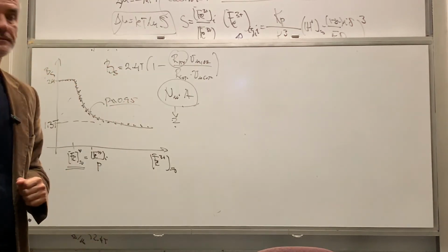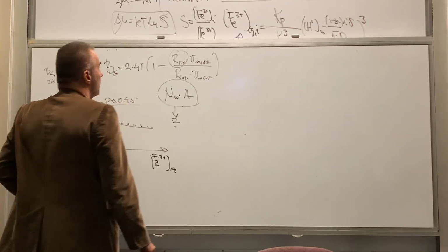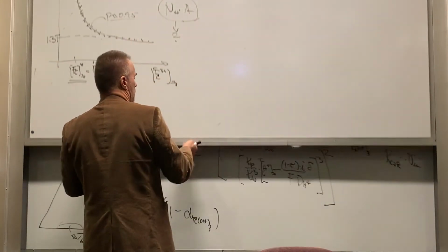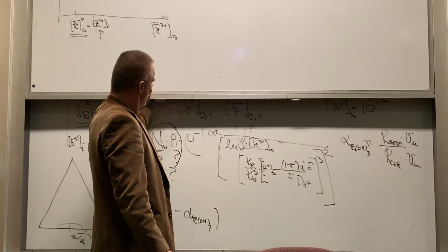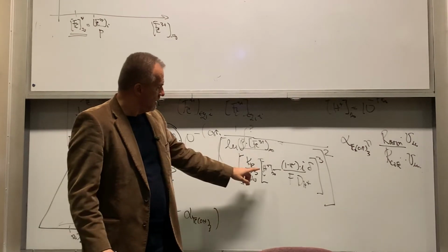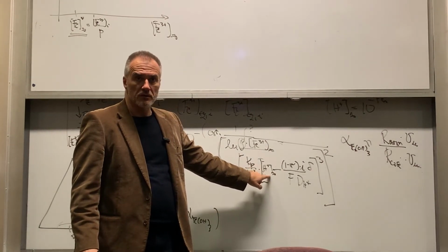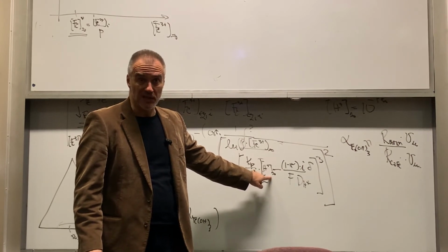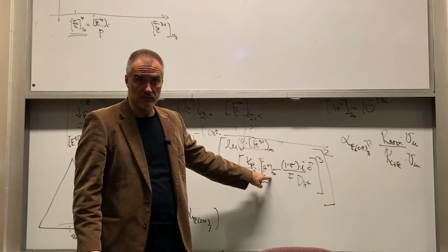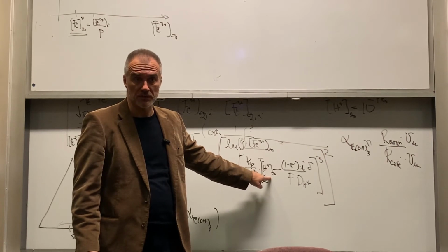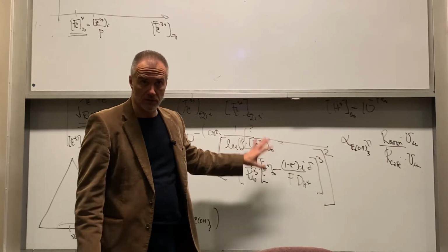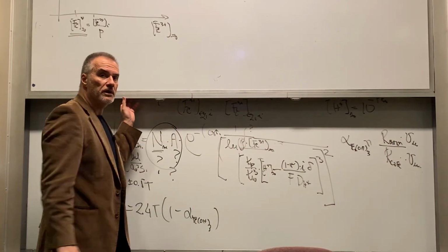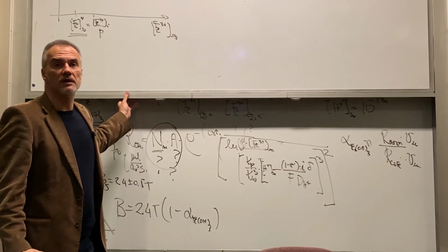For example, if you look at this equation, I just want to show you. You can see that in the model, the pH of the bulk, the concentration of iron, and the concentration of hydrogen in the bulk, which is your pH measurement, is part of the whole equation. You can now say, what if my pH probe is not reading correctly?